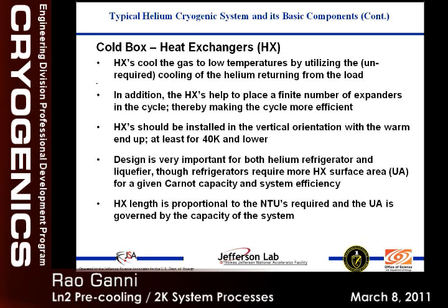And they should be oriented vertical, especially below 40 Kelvin, because now your density gradient on the high side is catching up with you. If you put the heat exchanger stack horizontal, say 1 or 2 feet high, the column height of the dense fluid gives a high pressure at the bottom, which gives you a higher flow through the lower stack than the upper stack. So you already have an imbalance right there. And when you are designing 98-99% effective heat exchangers, you will not get there with that kind of factor.